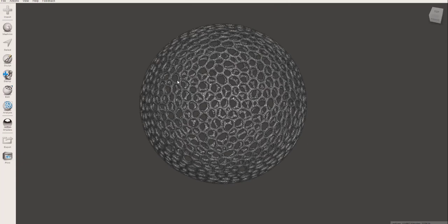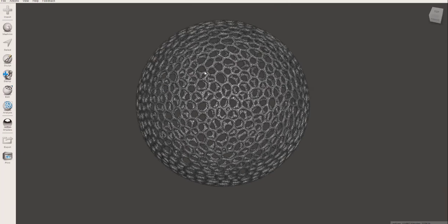So make sure if you just want one outer surface of Voronoi patterns, make sure your model is just a surface model, which is of course very easy to do in almost all the modeling software, SolidWorks, Fusion, whatever. So yeah, that's basically it.